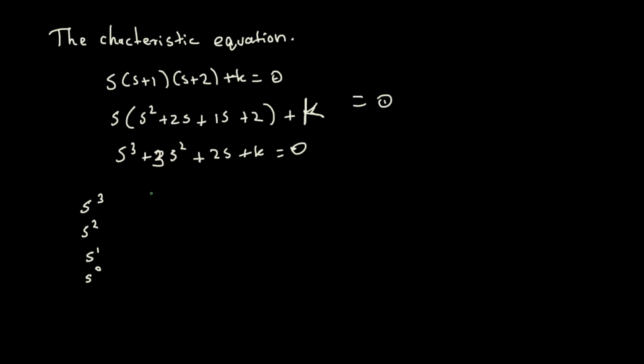And for s cube, what we have is 1, the coefficient, and the unused term is 2. The one next to it is 2. And s square is 3, and the unused term is k. Okay, we take like this, we only take care of cube and square. If I'm looking at the odd number, I look at the next odd number, the coefficient is 2, and then I look at the square and the next even number, you can say s power 0, so that one is k.